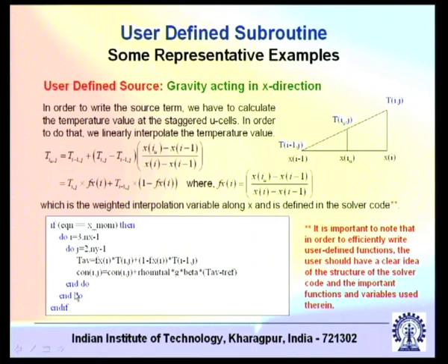So then we are writing, this con is the constant source term, like Sc plus Sp phi p, that Sc we are calling as con. So con I comma j equals con I comma j, that is whatever was initialized, plus rho initial, that is the reference density, into g into beta into (T average minus T reference). So that is how you simply implement the natural convection.